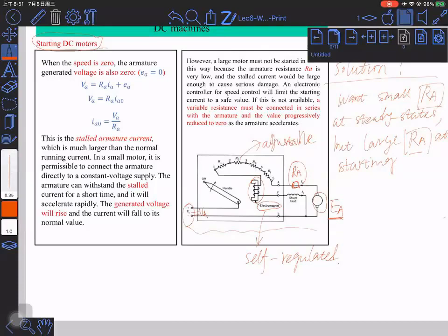If we start the circuit, because we have the shunt field winding providing the field current, which is independent of the armature circuit. And if there's a field current, the electromagnet is energized, and then it attracts this handle to position 1. If it's in position 1, we have the total adjustable resistor. It's going to be R1 plus R2 plus R3 until R4, and then plus RA.